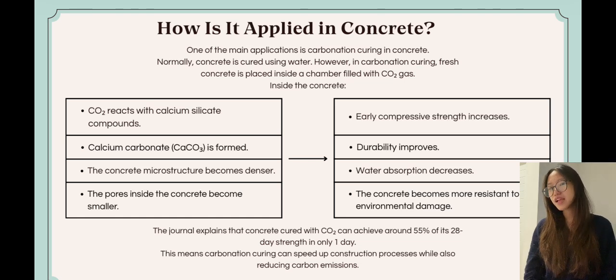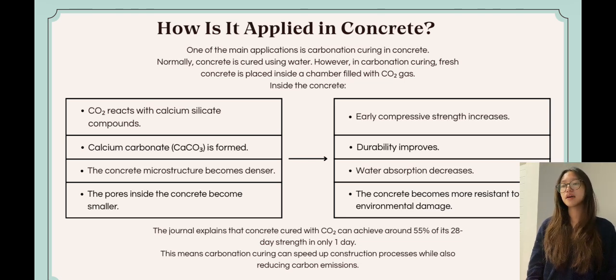The journal explained that concrete cured with carbon dioxide can achieve around 55% of its 28-day strength in only one day. So this means carbonation curing can speed up the construction process while also reducing carbon emissions.